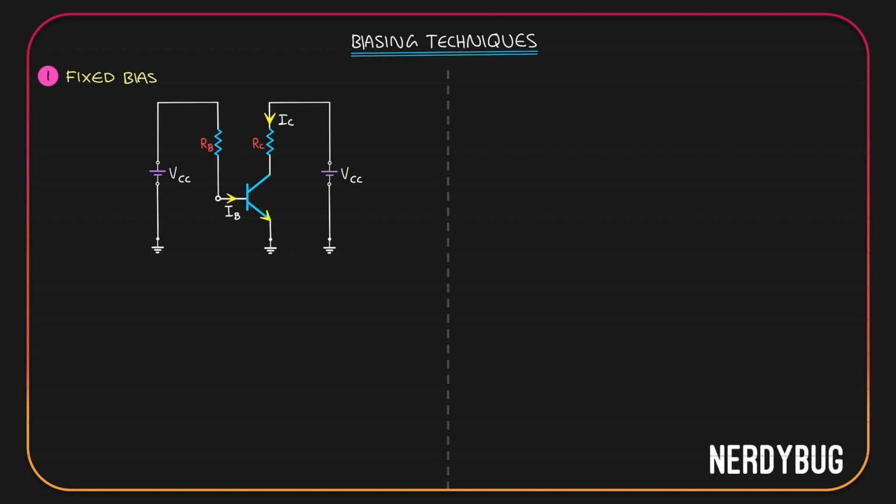Let's apply KVL in the base emitter loop. I'll start from this point and go clockwise. I can see VCC from negative to positive. As I go forward, I can see RB. Current through RB is the base current in this direction, which means positive potential is here, negative potential is here. Its direction is opposite to VCC, so I will write minus IB RB.